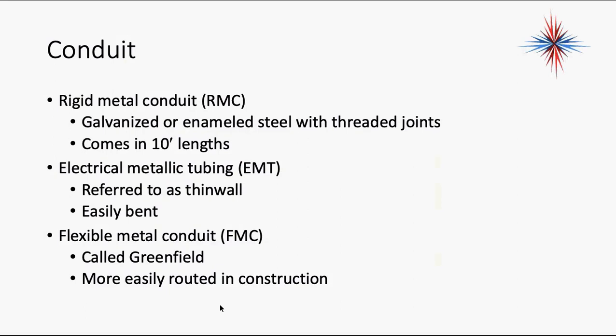Conduits are rigid metal or electrical metal tubing or flexible metal conduits, found most often in commercial environments, with one exception. Recent electrical code and recent mechanical code says that anything installed next to a boiler or a furnace has to be in a conduit. So you may see, from a ceiling in a basement down to the furnace or boiler, a conduit. That's because it's required, because it's heat resistant. It prevents fire. And basically that is how we take a look at electrical plans.